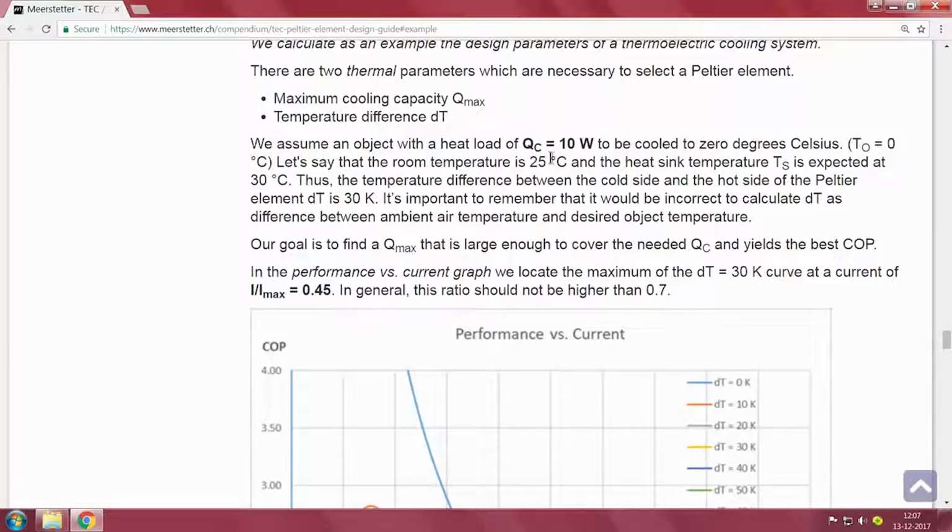Why 25 is taken is, this is the standard condition in which most testing takes place, and then as I said, in your practical example, you can probably go up to 40 degrees. 40 degrees is a reasonable thing, and generally wherever we use our equipment, probably the ambients are all controlled, and just around the electronic equipment it is relatively easy to maintain 25, maximum it can go up to 30. The room itself can be a little higher.